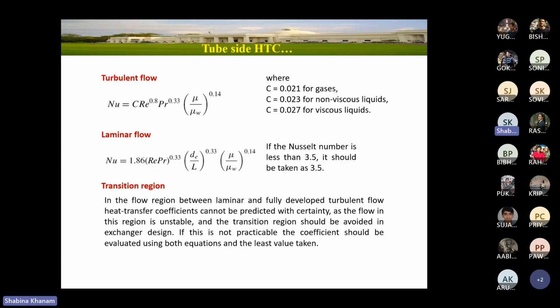Okay, and then it will complete the whole length of the tube, reverse back, and then enter another half of the tubes. I hope you are getting my point. So once it is entering the tubes, we can calculate the velocity, because you are already aware of the cross section area, density and all. So you can find out the velocity from the flow rate.